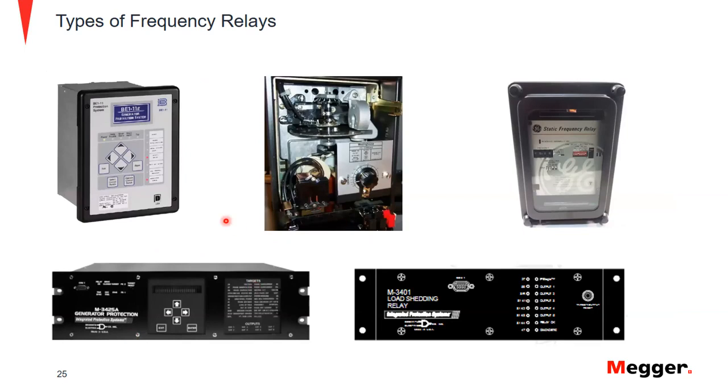So these are a few types of frequency style relays. We can have a little newer microprocessor based, comes in different shapes and sizes. We have that old CF1 there. I think they're still in service today. I have tested a few of these old guys years ago. And then we also have the old static relay, which is GE, and these guys are still around as well. And then even some manufacturers are putting out their own load shedding relay, which is just specific for that particular application. So in general, the frequency element can come in all shapes or sizes, actually.